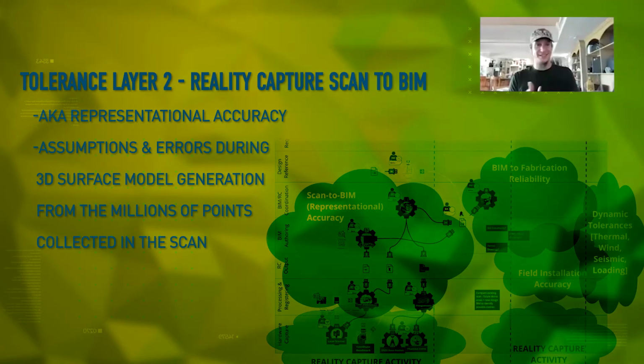But yeah, so that matching up of one scan to another scan is something that we typically talk about in terms of the local accuracy of the registration, scan to scan. And then you've got your global accuracy, of how accurate all of your scans are relative to the real world conditions. Because all measurements suffer from chain error.